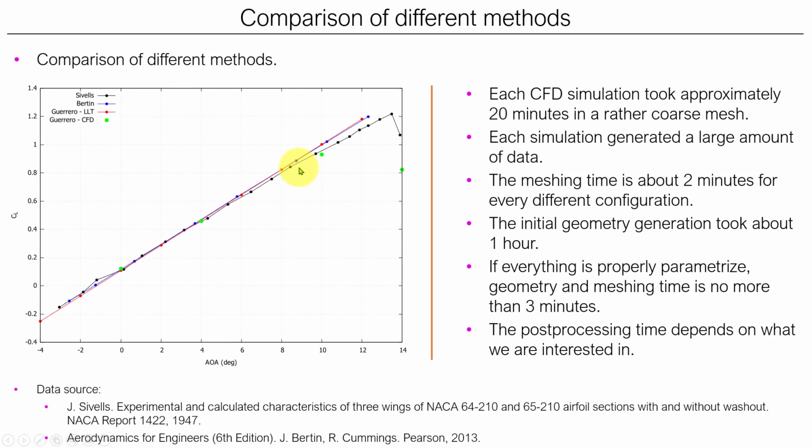The advantage of CFD, as you will see, is that you are going to have an instantaneous snapshot, can be in time or iterative marching, of what is going on. You can see how the flow is evolving all around your domain. Something that you cannot get using the potential methods, and also something that in experiments is very difficult to get. You cannot enter into your geometry and measure all around. Here in CFD, you can do everything.